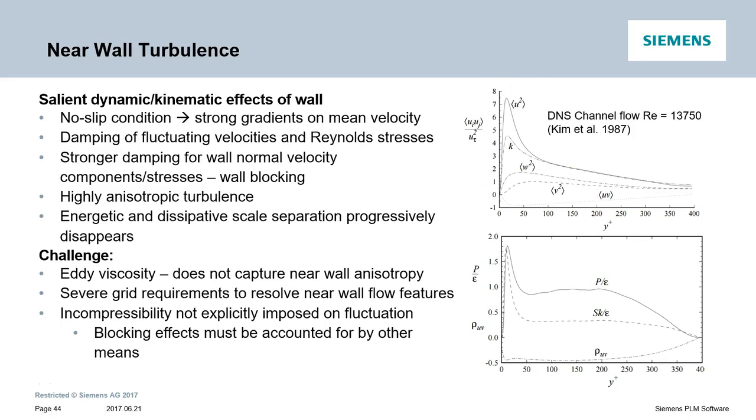Another characteristic feature is that the size difference between the energy containing and dissipative eddies gradually decreases as we approach the wall. And capturing this extremely complex near wall behavior is still a key challenge in turbulence modeling. The eddy viscosity models are not able to capture this wall anisotropy, and we need excessively refined grids to resolve near wall flow features, because now larger scales are of the same order as my dissipative scales.